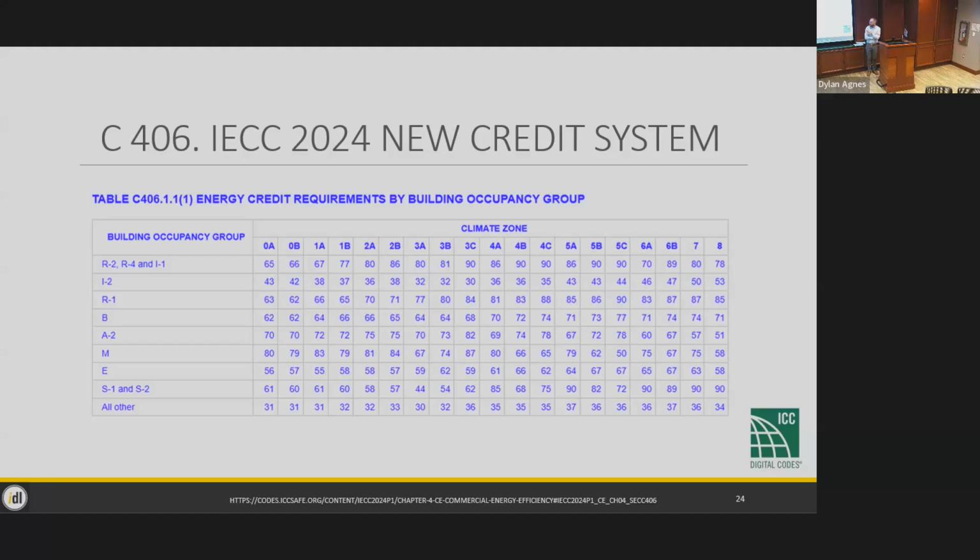One thing that I didn't mention because I was going to show it online is that there are additional equations for 406 in 2024 that factor in additional renewable energy credits. Those are redlined out in the Idaho proposal. In the IDAPA rules going before the legislature, there's no energy monitoring required, and there are no renewable energy credits that are permitted. I'm not going to push you to add any renewables. It's not saying you can't. It's just saying you're not going to get credits for those in this table.